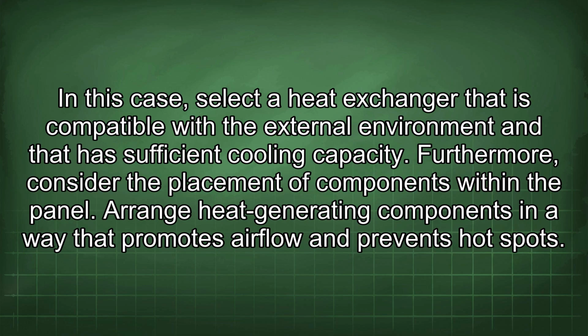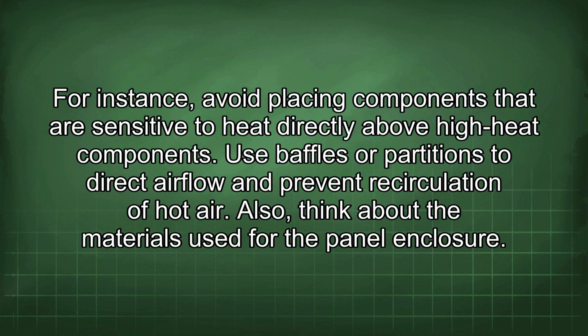Furthermore, consider the placement of components within the panel. Arrange heat-generating components in a way that promotes airflow and prevents hotspots. For instance, avoid placing components that are sensitive to heat directly above high heat components. Use baffles or partitions to direct airflow and prevent recirculation of hot air.